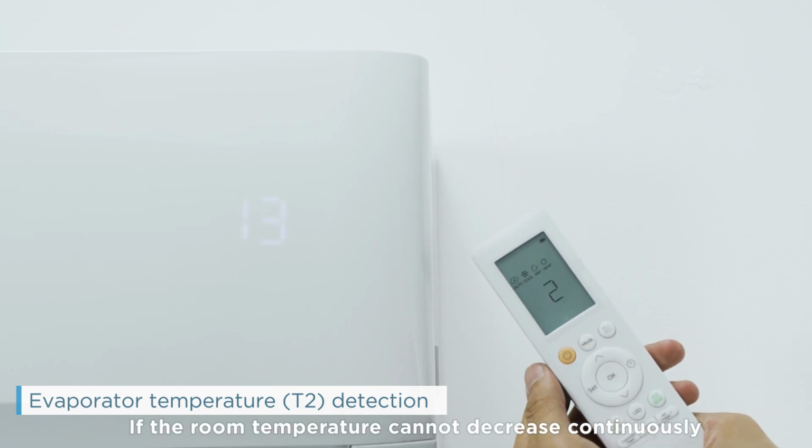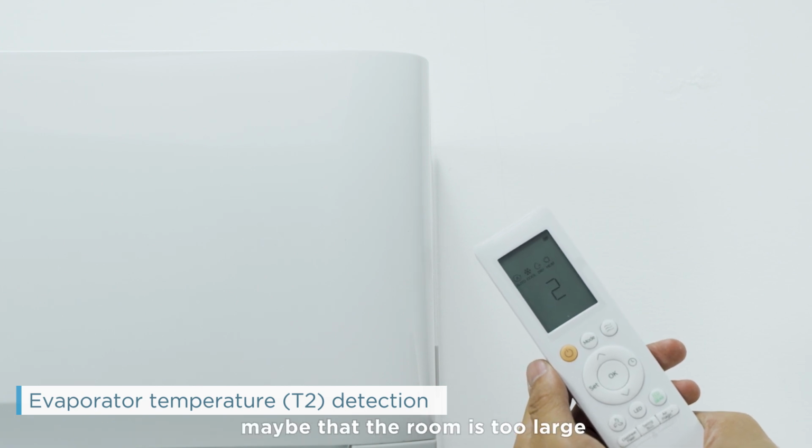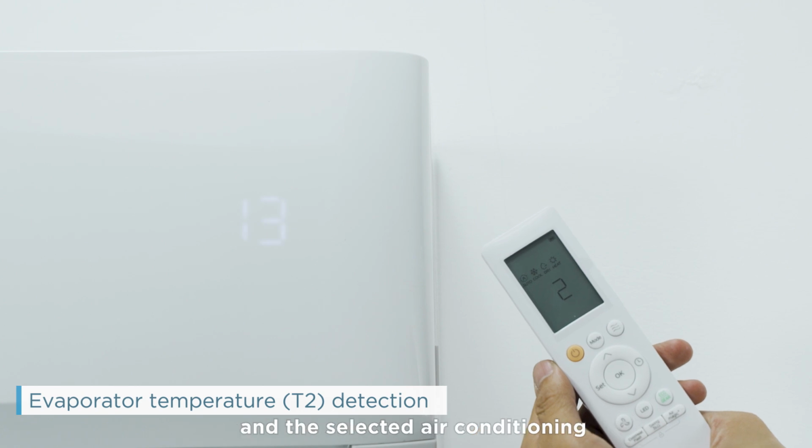If the room temperature cannot decrease continuously, the possible reason may be that the room is too large or the insulation effect of the room is poor, and the selected air conditioning cooling capacity is too small.